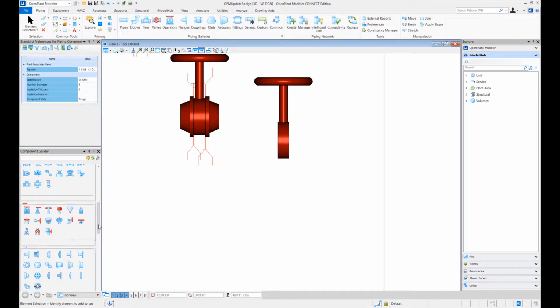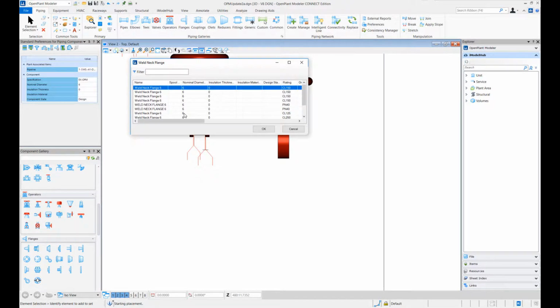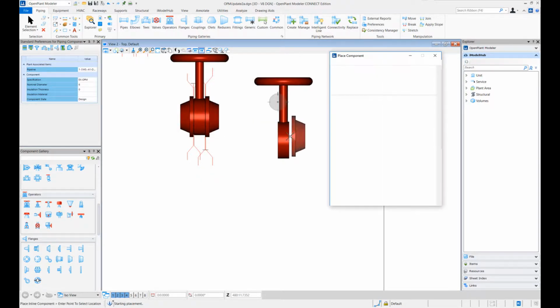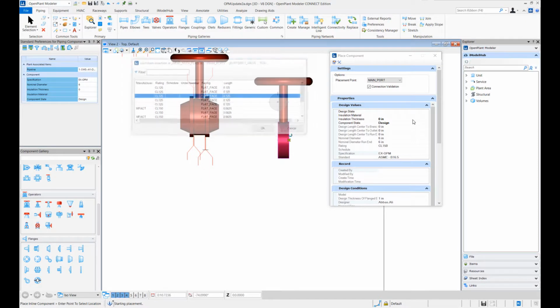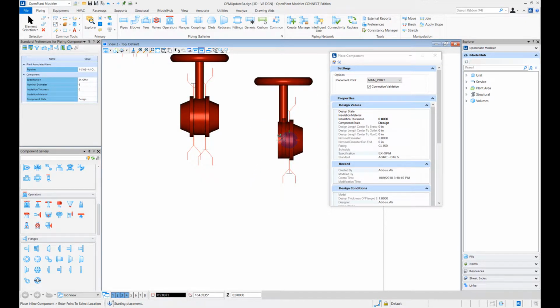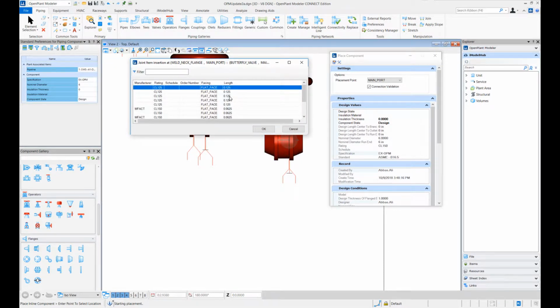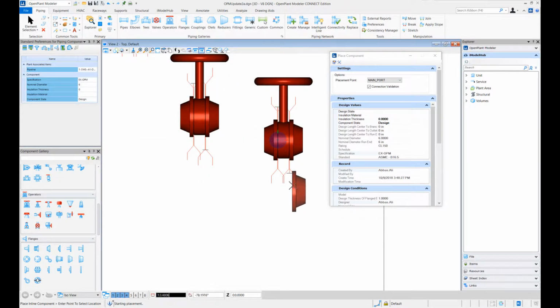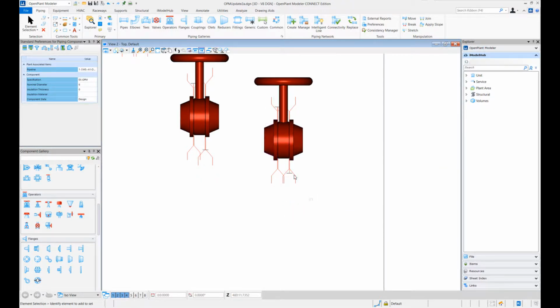So with this wafer lug end, when we place mating flanges, it puts up gaskets on both the ends as well as fully threaded machine bolts at both the ends and one set of partially threaded through bolts. So this is a combination of a lug and a wafer joint, and it places three sets of bolts and two sets of gaskets. So let me just quickly check.